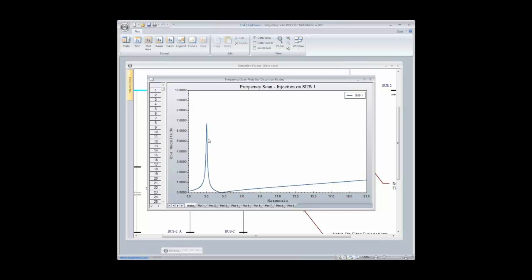Every time you have a filter put on a bus of some form, you're going to be pinching it down to a filter point, and it's going to react to that and create a first parallel resonant point below the filter. So for this fifth harmonic filter, we have a first parallel resonant point, which in my opinion is not really in a very good place. I would recommend that you position this away from the third harmonic.